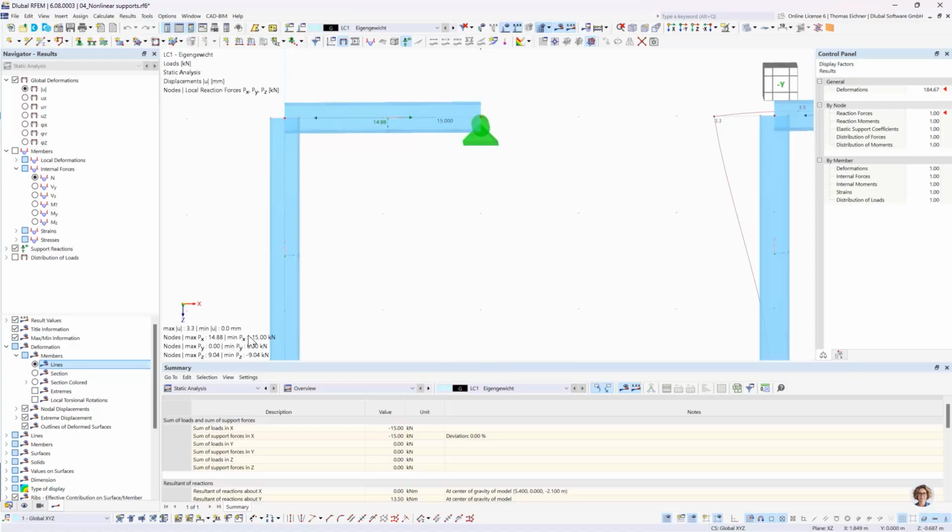It's directed in negative x direction. So there will be a force to that support in negative x direction, and for that support to be able to withstand, well, or to have zero deformation, it needs to have a reaction force in the other direction. That's why this reaction force is defined in positive.